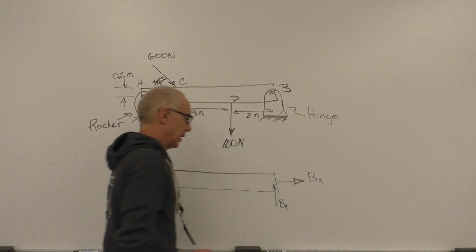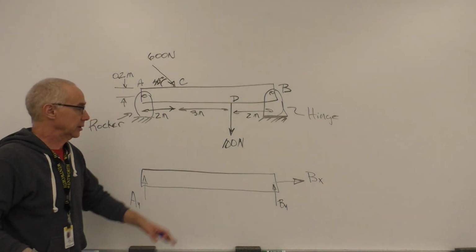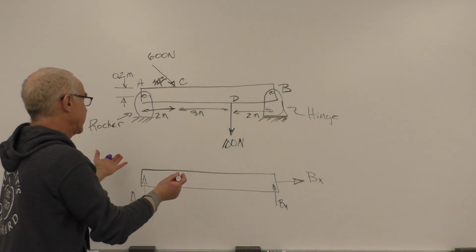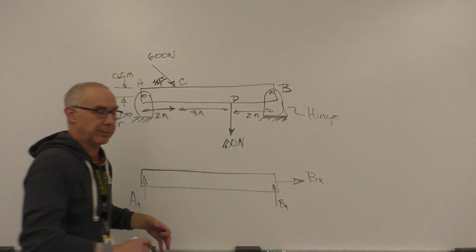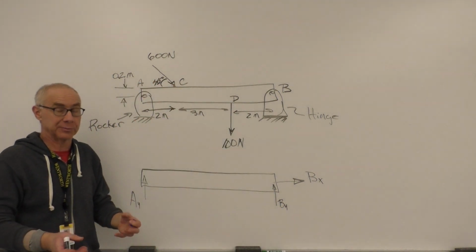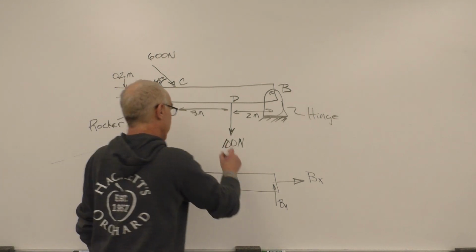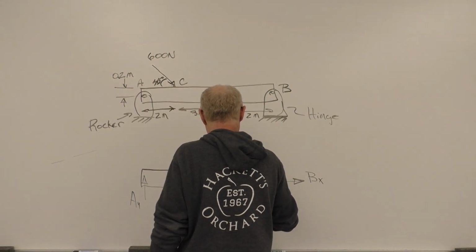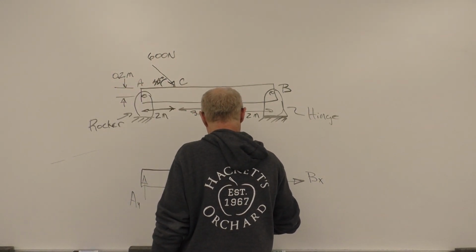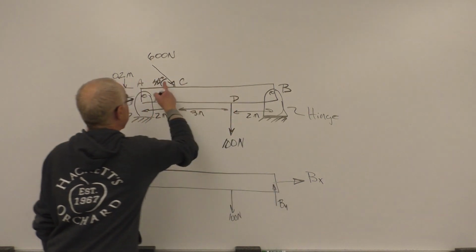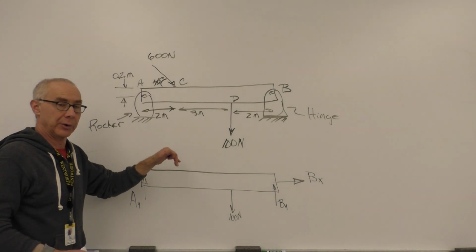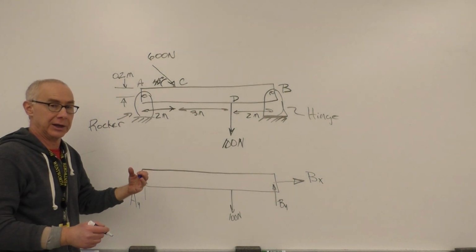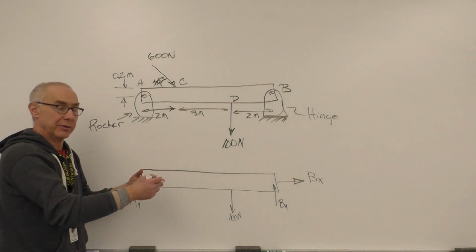And again, so that's my vertical support reaction at that end. And then we have to finish out our free body diagram. In other words, the free body diagram is not just the support reaction, but you have to have the imposed loads. So we'll have this 100 newtons here. And over here we can break this into its x component and y component. And I encourage you to do that because it'll make it easier when we calculate the sum of the moments.